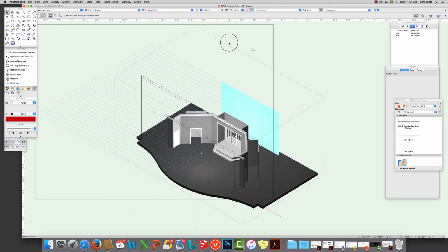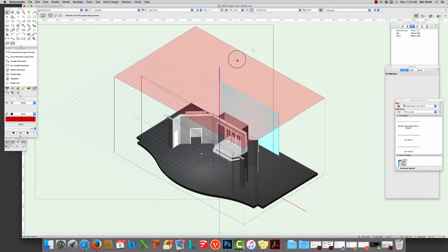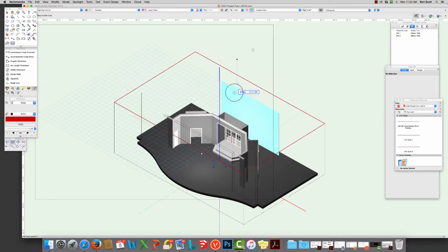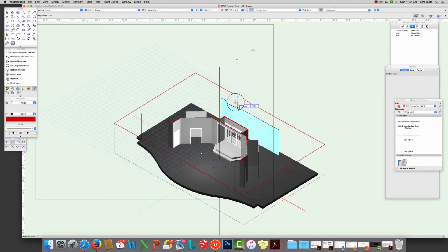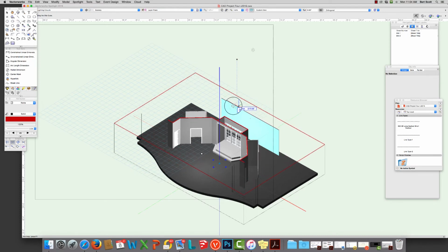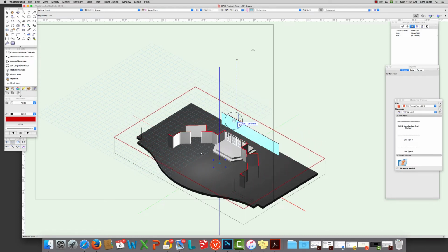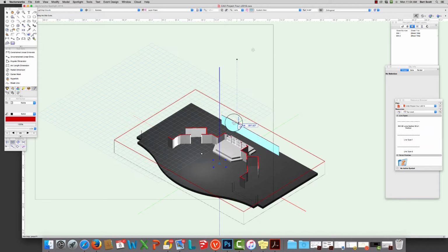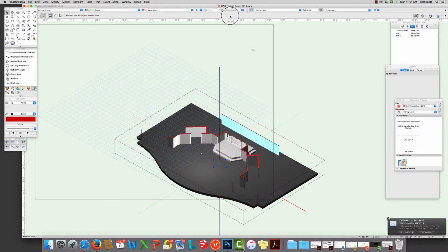To go a little more in depth, if we remember, we talked about the ground plan being the set cut off about 4 feet above the ground. So I'm going to do a little drafting magic here. I'm going to start slicing the set. If you see what's going on, I'm just removing parts of the set. I'm going to take it down to about 4 feet off the ground. And hopefully you can start to see this is how the ground plan develops.